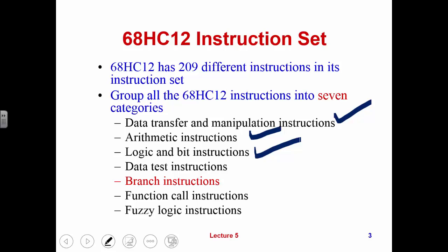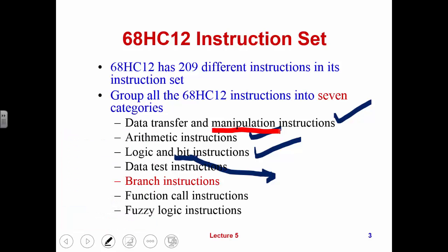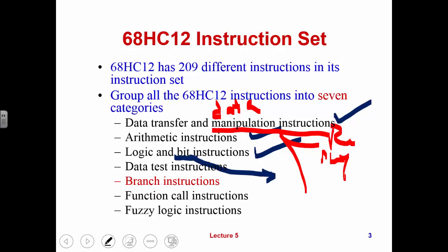When we go to the bit manipulation, it's mainly about clearing bits or setting bits. They are designed to play with individual bits of a value in memory or in a register. Make sure those manipulations are different from data manipulation. Those in the first category are about data manipulation, mainly rotation and shift. We have arithmetic shift and logic shift. They manipulate a whole value.